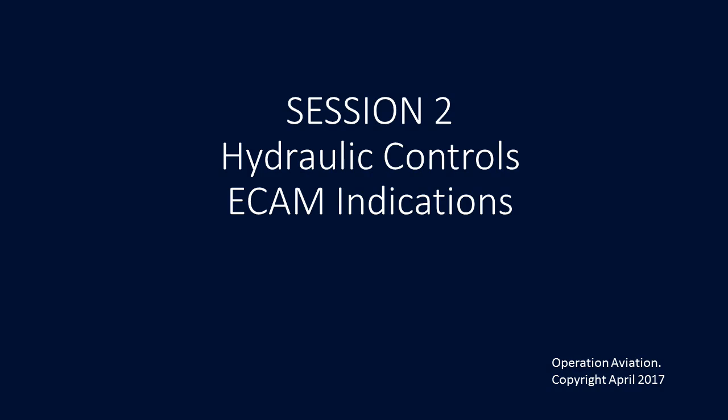So PTUs, these are normally placed in the auto mode. When the push button is selected in the auto mode, the PTU will, on the ground, perform a self-test when the second engine is started. It also will automatically engage when differential pressure between the green and the yellow hydraulic system reaches a predetermined value.